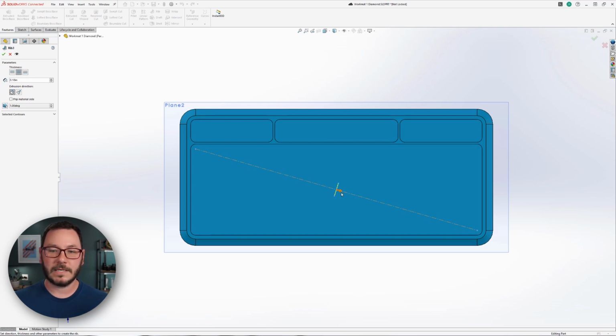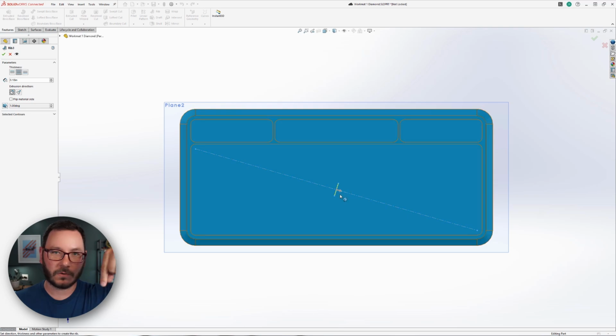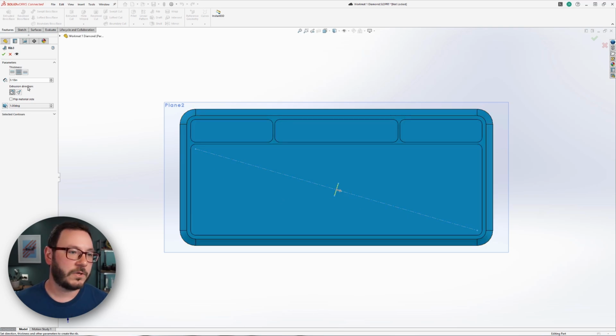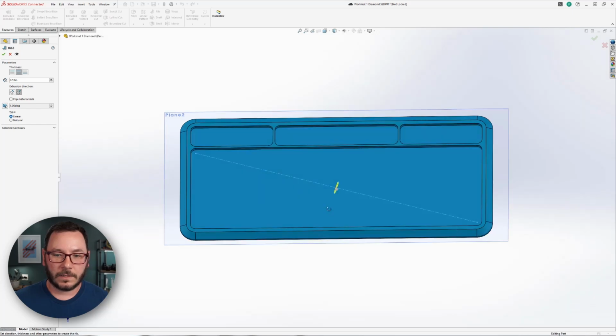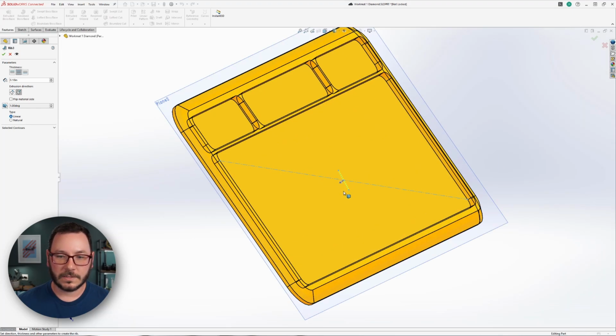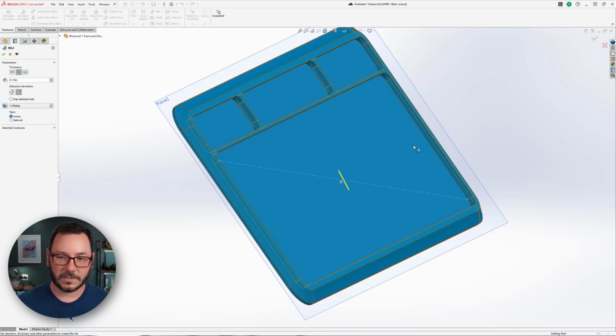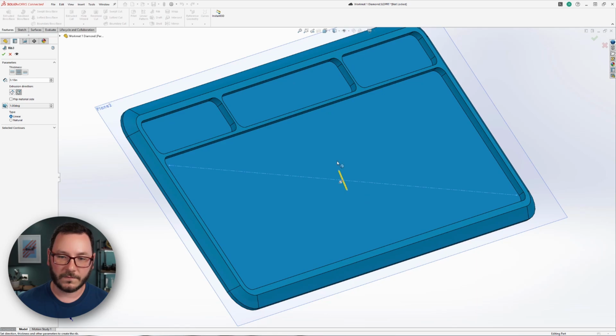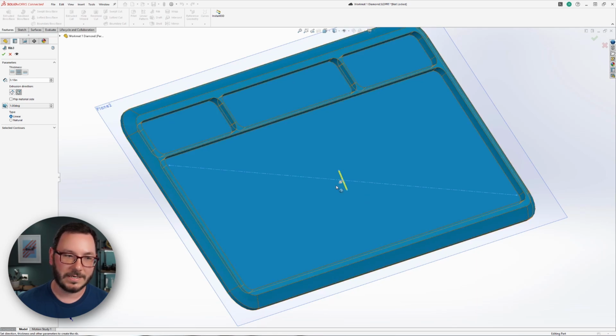So in this case, we have the rib pointing off to the right-hand side, which is not what we want. We want it to go down. So we'll come over and switch our extrusion direction to downwards. And let's rotate over here so we can see. It's a little bit tough to see what plane we're on, but we're off of the ground here, and it's searching downwards.